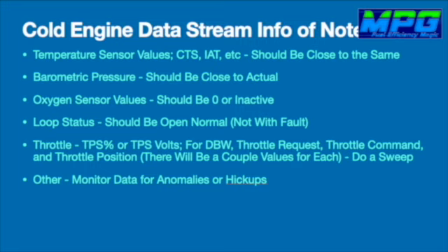Then look at barometric pressure. You should have a barometric pressure reading on most vehicles, and you can just check your local weather service to see what the barometric pressure is where you are. It should be pretty close.